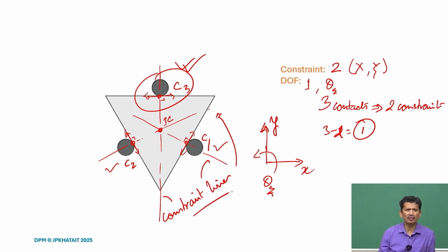If we try to impose and use all the 3, what will happen? We need to have very high tolerance parts, or they will start fighting because which two constraints should provide the 2 constraints, which is x and y translations.